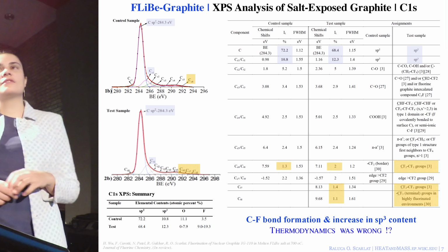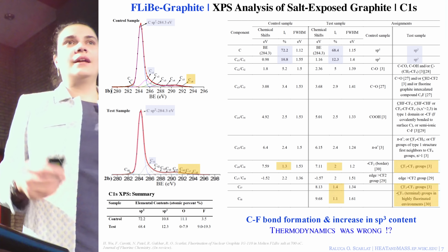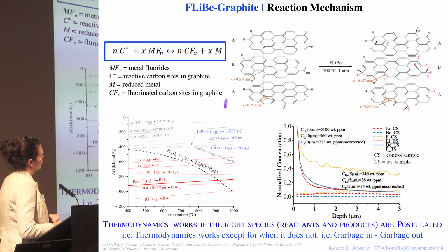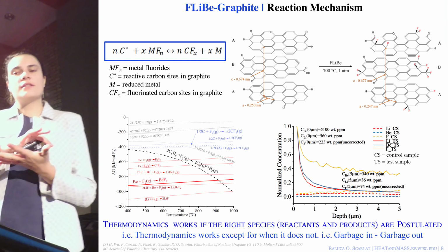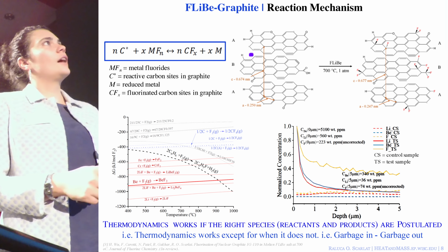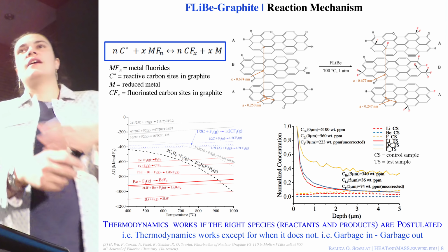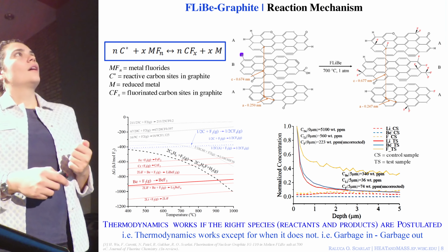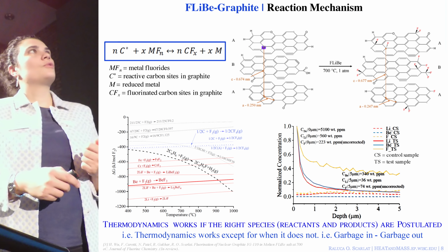And so how is this possible? Thermodynamics predicted that this shouldn't be possible, and nevertheless it's happening. If we look closer at graphite, here are the graphene sheets. Nuclear graphites are not single crystal graphites. They're not formed out of an infinite sheet of graphite that never ends. They have edges. And those edges will have sites that are unsatisfied bonds in some shape or another.